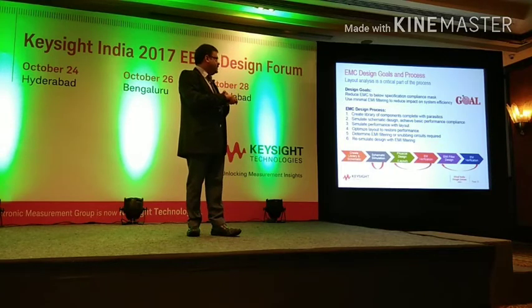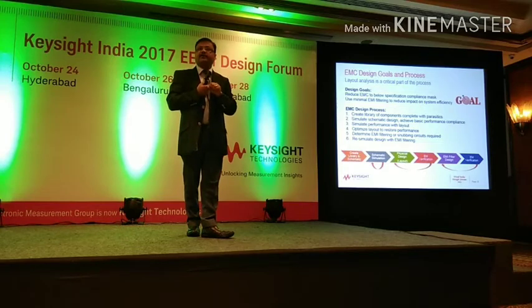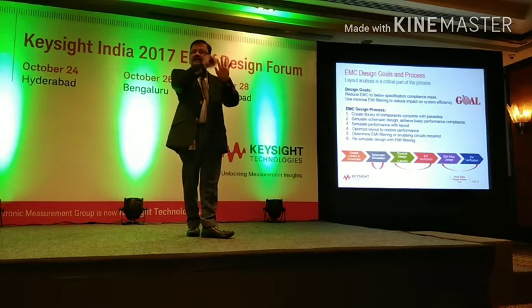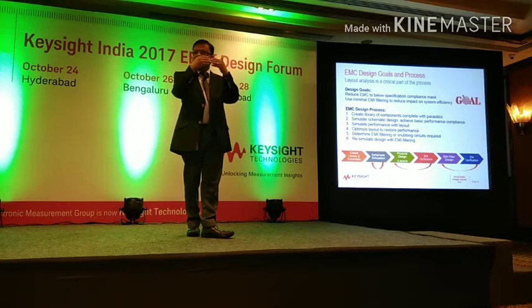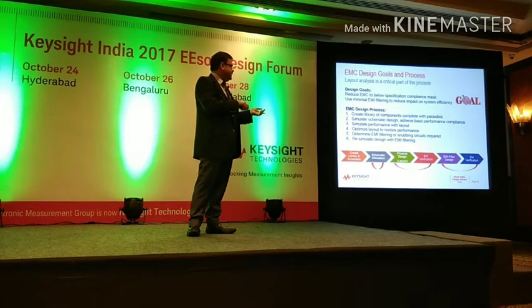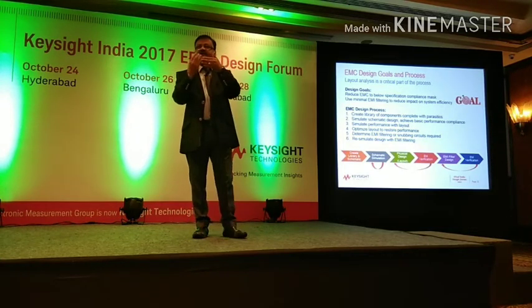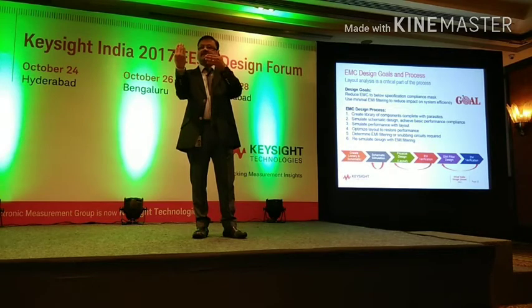Simulate the performance with layout. Take layout parasitics into account. Don't treat schematic as ideal interconnection between the components. Simulate layout. See how this layout comes in between the components. Optimize the layout to restore the performance in case you see there is a layout parasitic. Something was working nice, just after having layout not working nice, that means it's a layout parasitic which is caused.